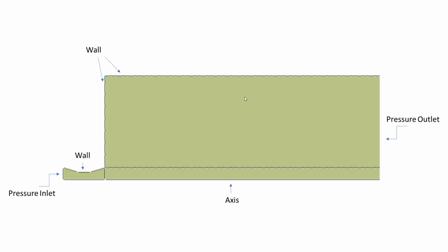Yeah, I'm going to explain 2D simulation of supersonic flow through a CD nozzle. So I'm going to take this kind of domain for the computational analysis. I'm not only taking the CD nozzle, I am taking the additional flow domain so that I can simulate the exhaust jet properties also behind the CD nozzle.